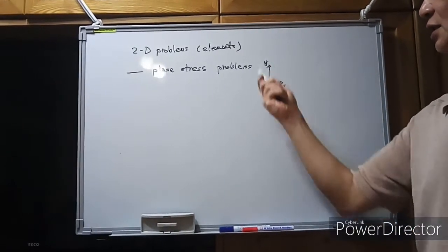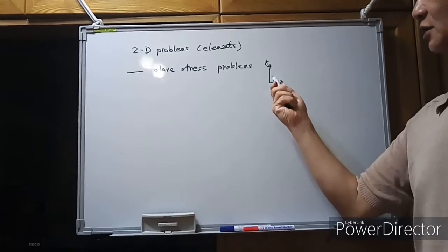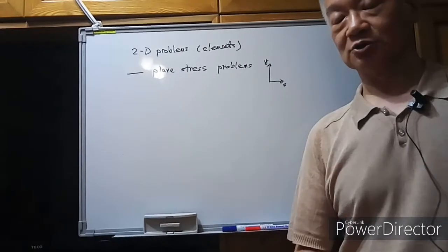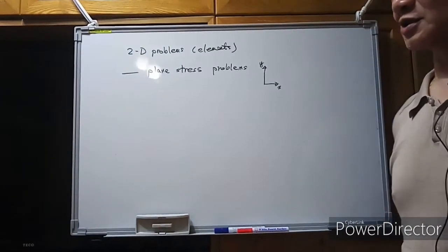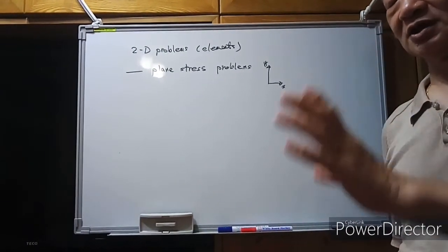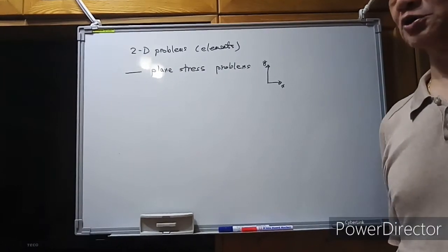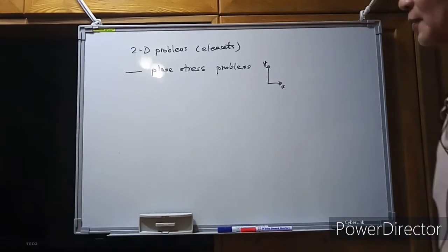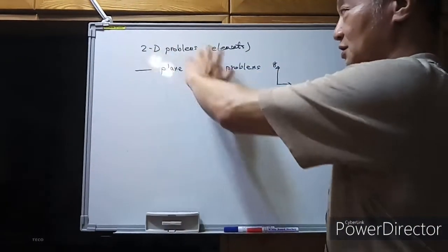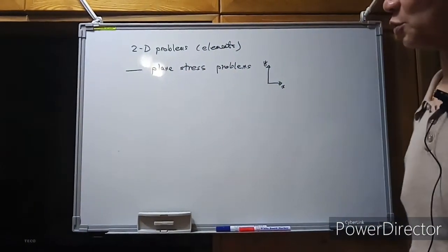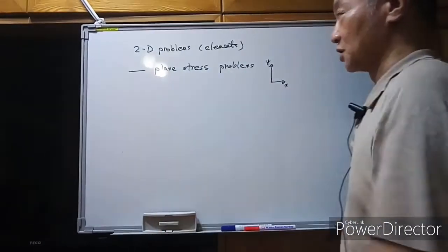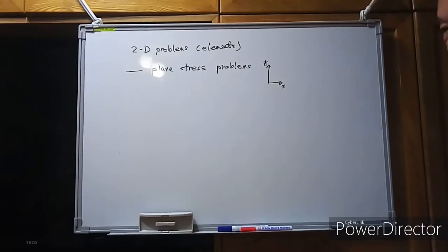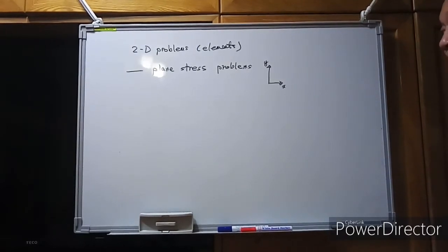The two-dimensional problems usually means that we can use a two-dimensional coordinate system to describe the geometry, the applied loadings, and solve the displacement. For those kinds of problems, they are called two-dimensional problems. The plane stress problem is a typical two-dimensional problem.